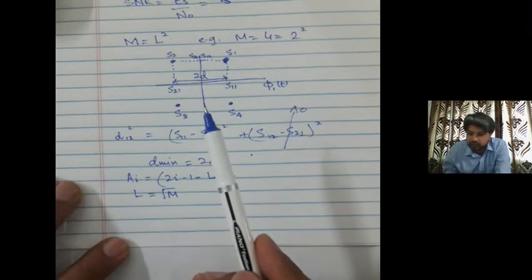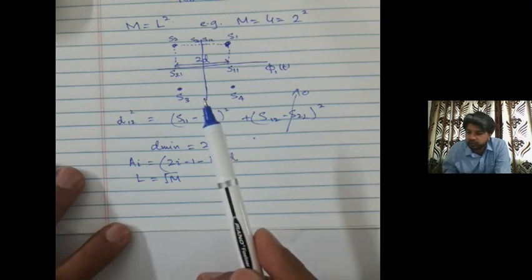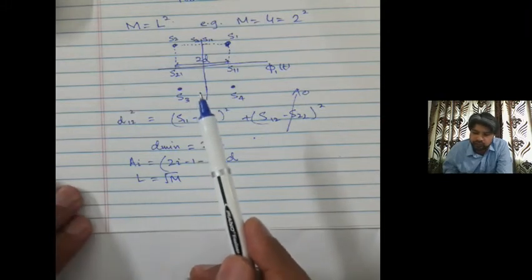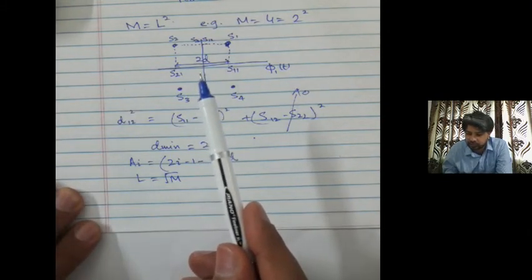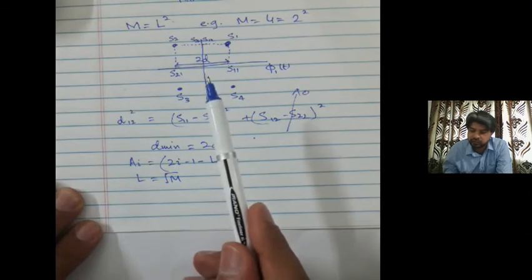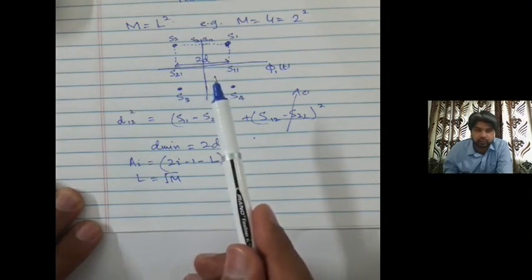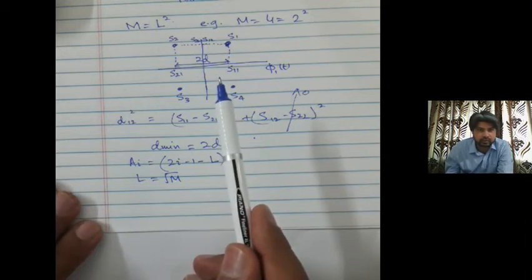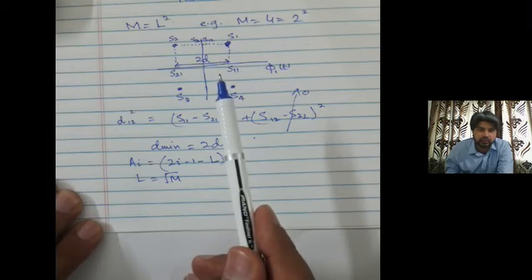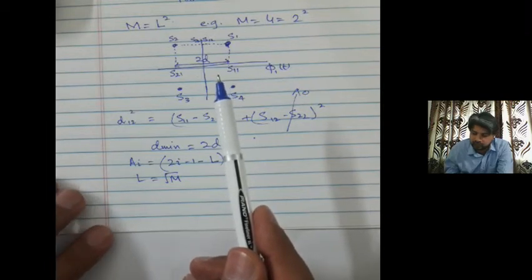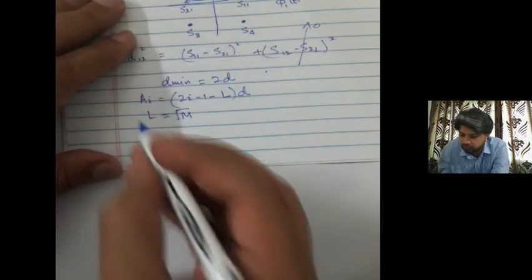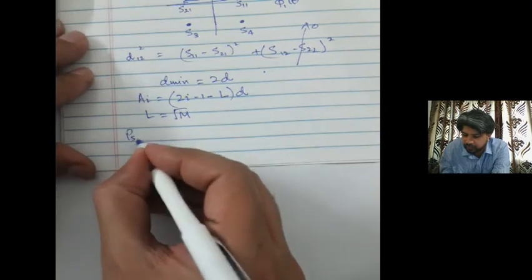Hence, you can think of the constellation of a quadrature amplitude modulation as two branch constellations, so as two 1D constellations, which are nothing but the projection of the constellation points onto the basis function. So rather than one 2D constellation point, you can think of two branches, and each branch is a one-dimensional constellation. And then you can compute what is called the symbol error probability of a branch. So if you want to compute that, the symbol error probability of a branch, let me call it.